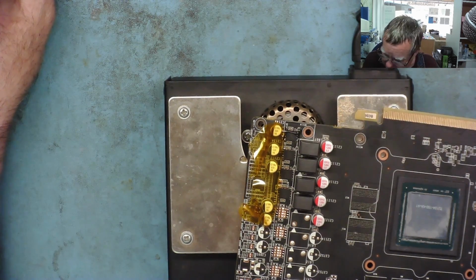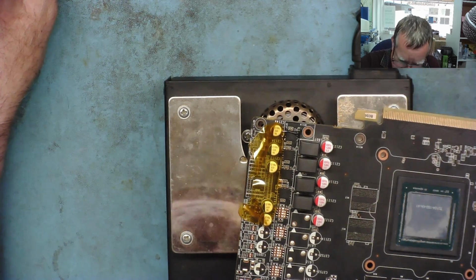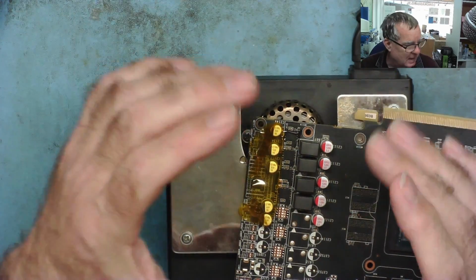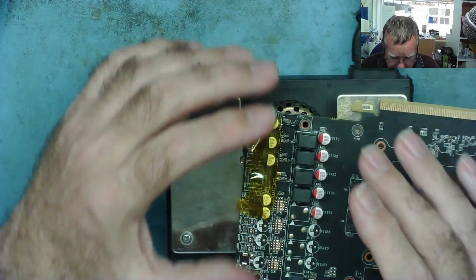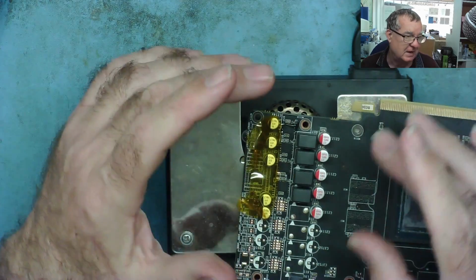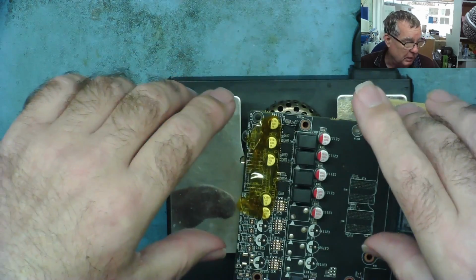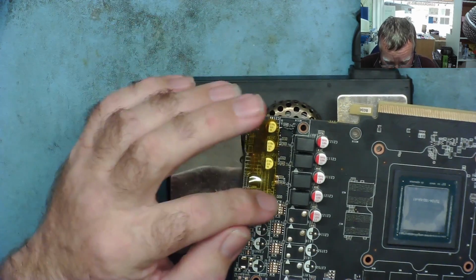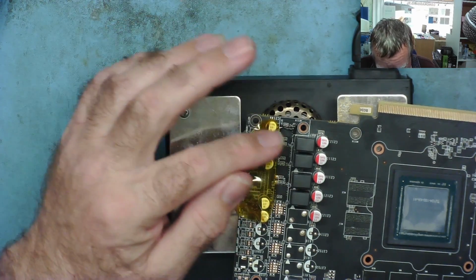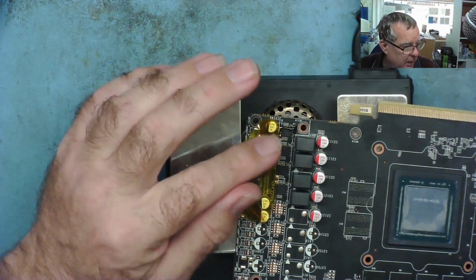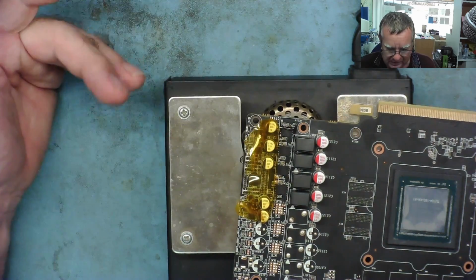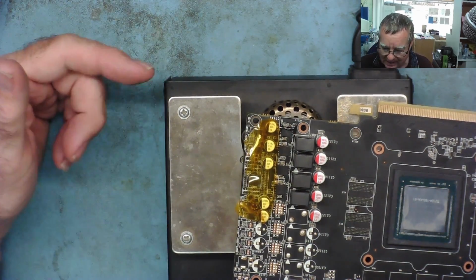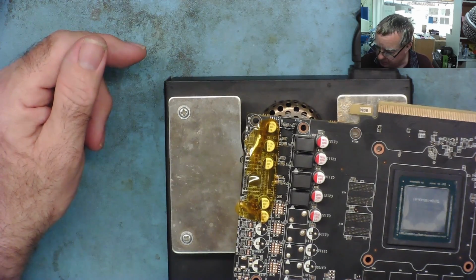Now these have by the driver some small surface mount components. Normally I would take a photograph before working so that I can refer back to that afterwards. If I've knocked something off the board or dislodged something, I can see where it goes. But with these, because they're all the same and it repeats the same circuit, the components next to each one is the same as the components next to the other one. So if I do dislodge something, in this case I can easily work out what it was.